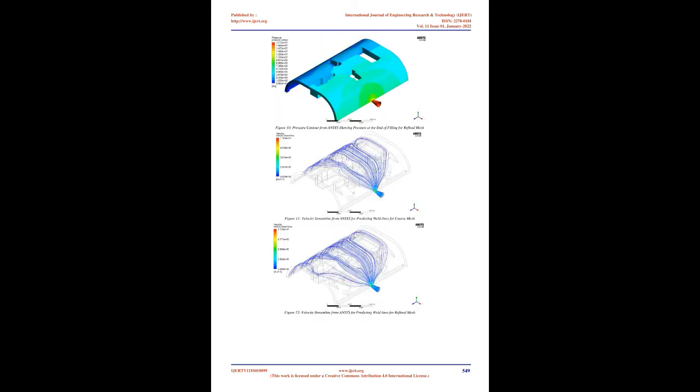The result from the study was plotted with the ANSYS post-processor, CFD-Post. Figure 6, Rheological properties of ABS, Autodesk Moldflow plastic slabs. The mesh was further refined and the study repeated to determine the effect of discretization error on the parameters of interest. The refinement resulted in 446,592 elements, and all 1,500 iterations ran without convergence.